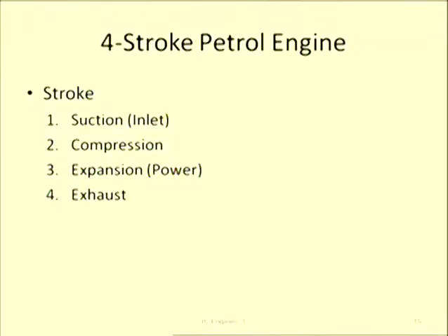Third stroke is expansion stroke or power stroke. After compression, in case of an SI engine, the spark will ignite and the combustion process will start. So the air fuel mixture will burn, and when it burns, it will create tremendous pressure and temperature, and that will apply some force onto the piston, so that the piston will move in the downward direction. That is called power stroke.